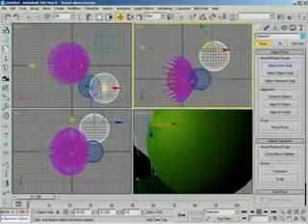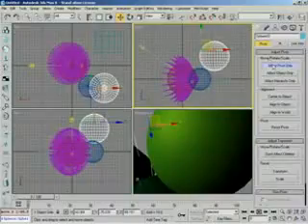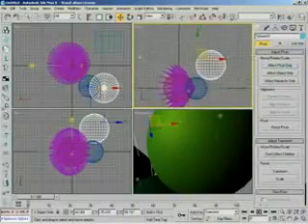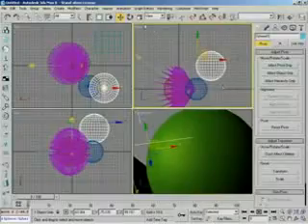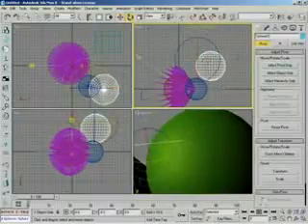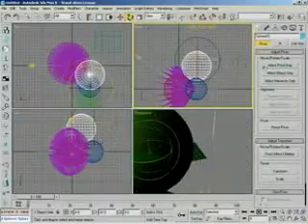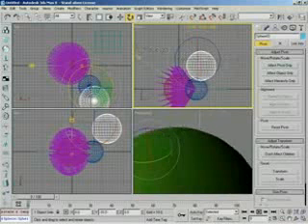Yes. So now, with the same example I gave a second ago, if you now turn that back off. Sure, turn it off. Now you'll notice our pivot is staying over there. Now if you grab that rotate tool again, look what happens when he goes to rotate it around Y. Now it's rotating around an entirely new point.